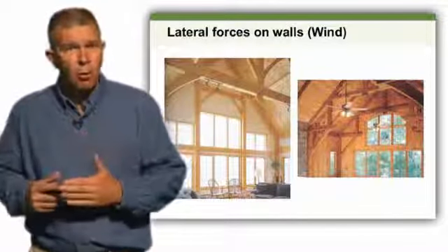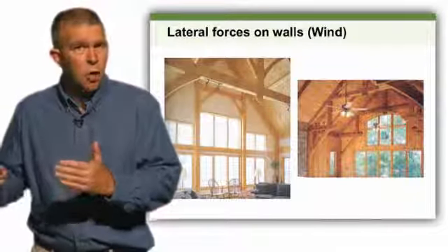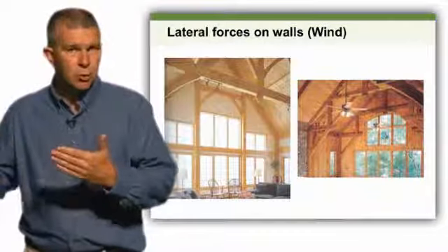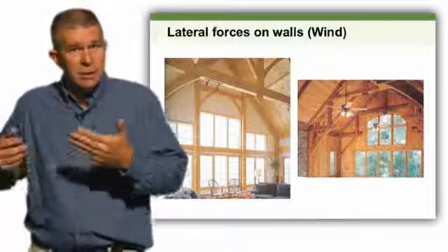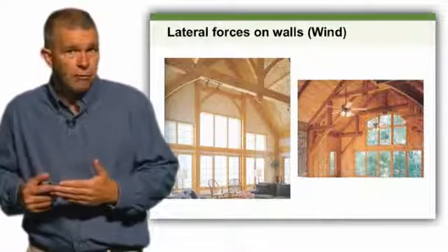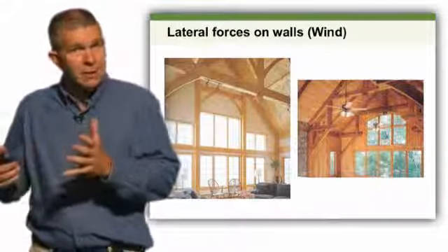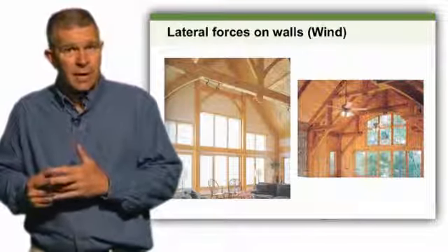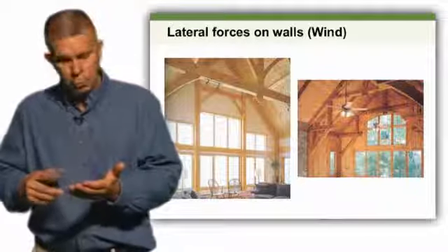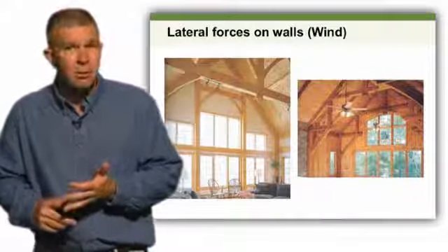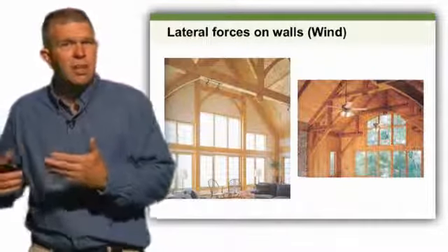Now both of these pictures are within timber frame structures, but again, the one on the right puts a big dramatic tall wall with a whole bunch of windows in it with no good way to resist the force, which is that wind. Now this panel is being asked to do an awful lot of work, and in essence, as the designer starts to calculate those loads, you may be required to put a lot of lumber or maybe even steel inside of this wall panel to resist that force.